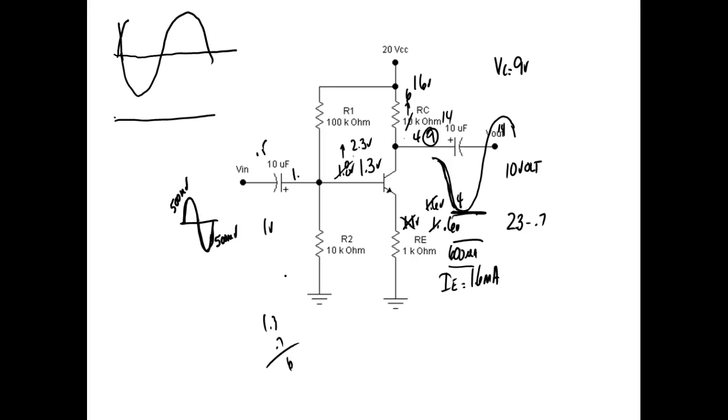So I can bring any type of AC signal in. Now, usually when we play around with amplifiers, this amplifier has what we call a bandwidth. If I try to put DC into this thing, this capacitor is going to block it. And these capacitors block DC according to a formula. You'll learn this in AC. It's 1 over 2 pi FC. So the bigger the capacitors you use right here, the better the low end frequency response.